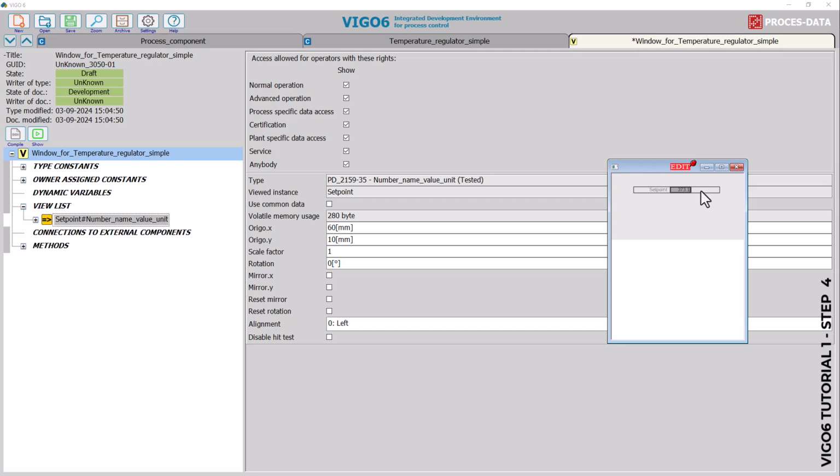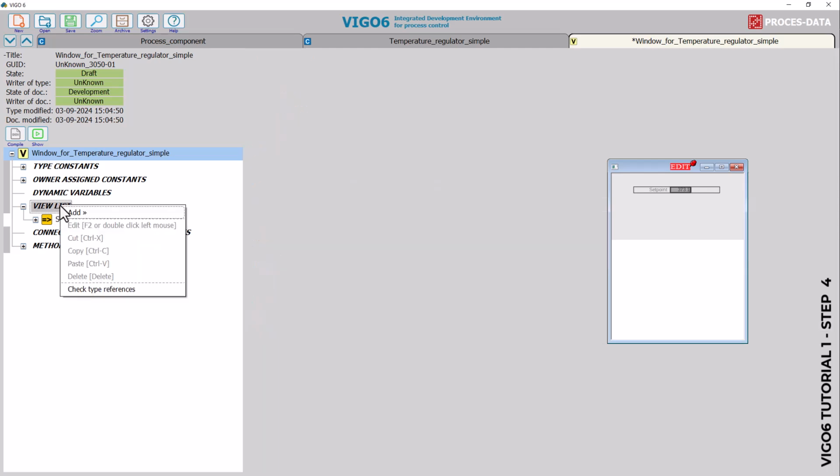The rectangles surrounding the name, number and unit are to indicate the maximum area the visualization may draw within, and is only shown in edit mode. On your view, you now see the element and you can drag it where you want on the screen. Add a similar view for the register actual temperature.